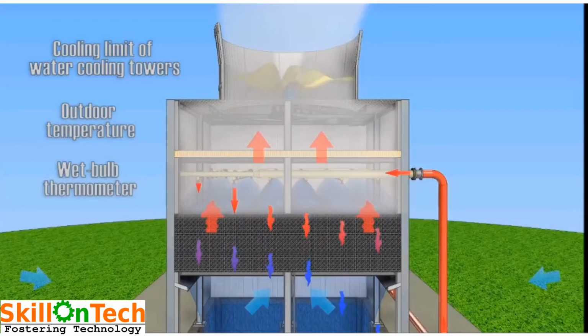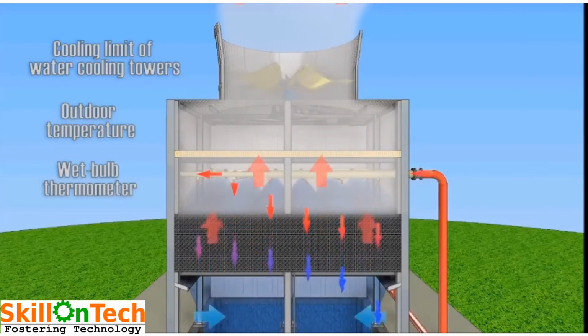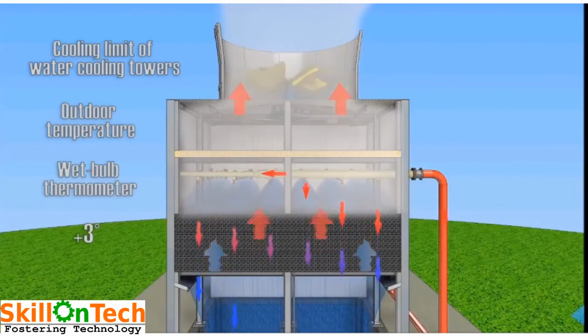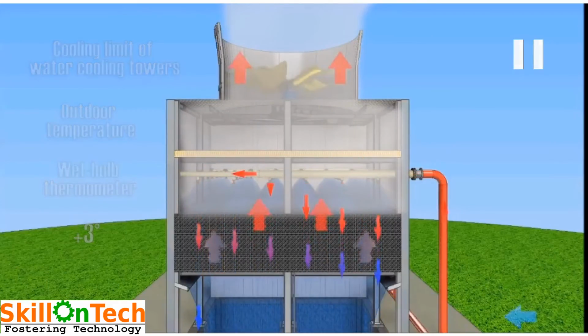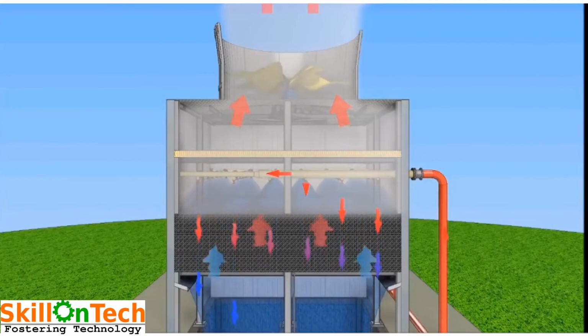One important term is range in the cooling towers, that is the difference between return header hot water temperature and cold water temperature. I will describe how to evaluate effectiveness of a cooling tower in my next video. The evaluation of cooling tower effectiveness is generally based on the temperature difference of wet bulb and cooling tower cold water temperatures.